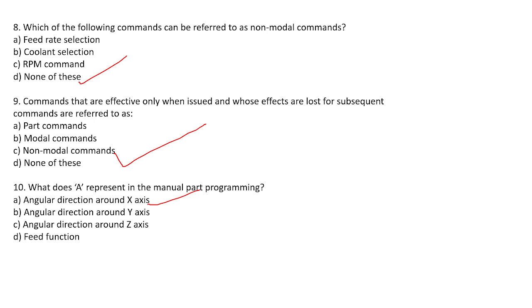Feed rate in machining operation is actually specified by G code commands, such as G01, G02, G03. Those G commands control the movement of the cutting tool in different directions at different speeds to produce the desired shape and dimension of the workpiece.